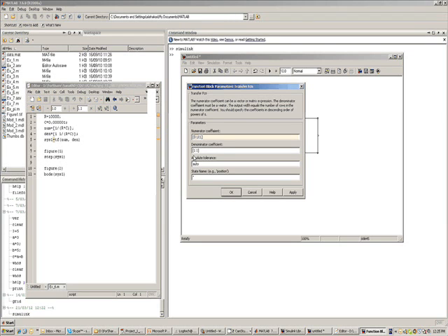Therefore, I'll type in the numerical value of R, which is 1 and 4 zeros, that is 10K, and C, I think it was 1 nanofarad or something, 0.1 with 5 zeros and 1. So that is the numerator polynomial.